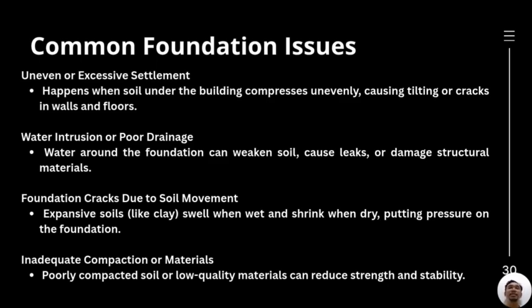The uneven or excessive settlement happens when the soil under the building compresses unevenly, causing tilting or cracks in walls and floors. Next is the water intrusion or poor drainage. The water around the foundation can weaken the soil, cause leaks, or damage structural materials.